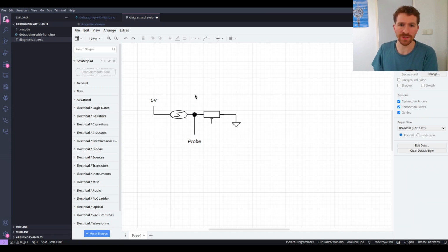The reason the voltage is going to change is because we're going to hold this light-dependent resistor up against the LED that we're trying to observe, right? And if we're able to do that effectively enough and remove some of the ambient light in the room, what we're going to see on the probe is the resistance of this change, and therefore the voltage drop here is also going to change, and we're going to be able to observe that as a signal on the oscilloscope.